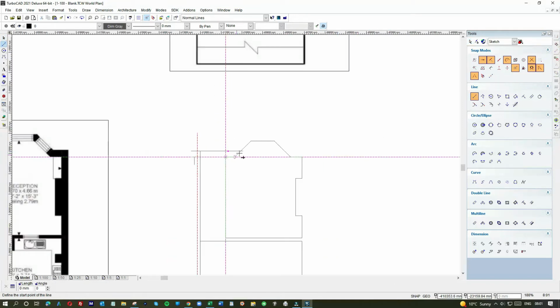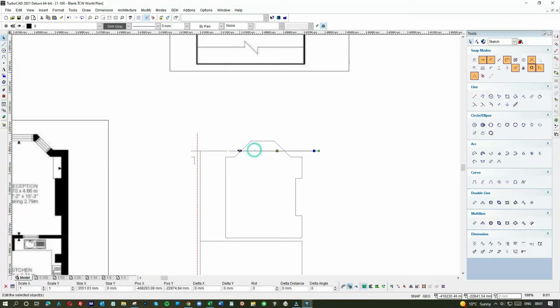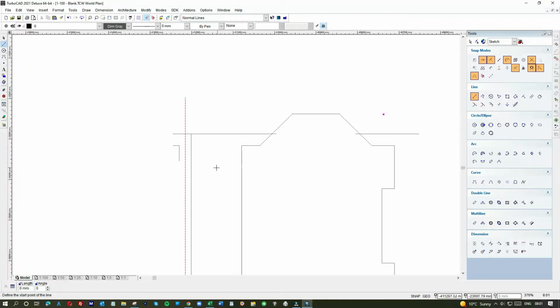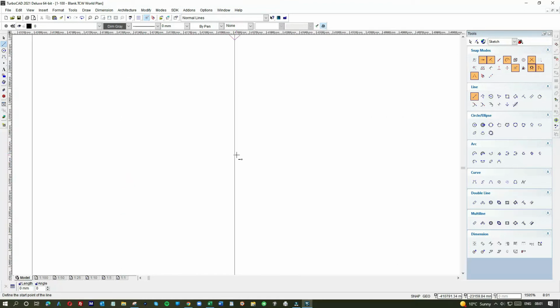Yeah, that'll be interesting. That was the internal measurement. Now this wall, this partition between the hallway and what would have been the lounge, again is a thin wall, 100 stud timber or block or brick, depending on the actual age, and some plaster on either end.